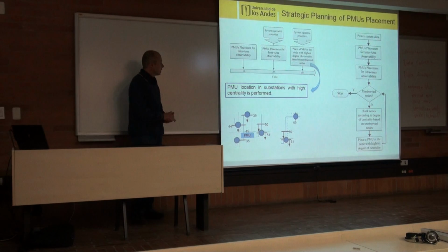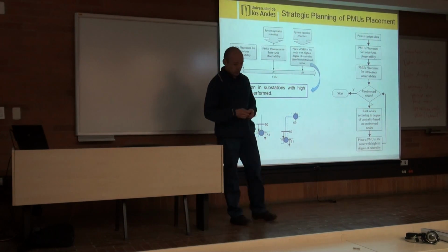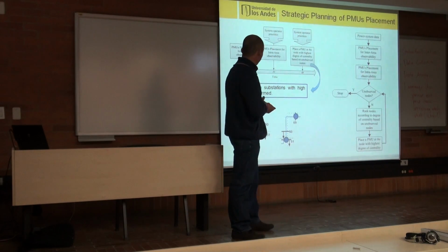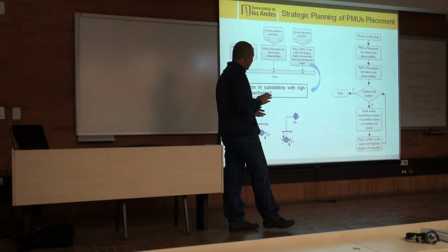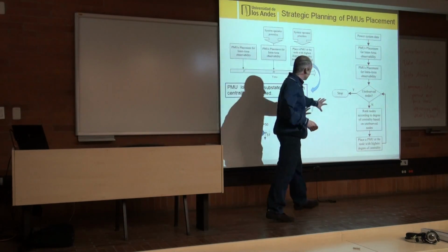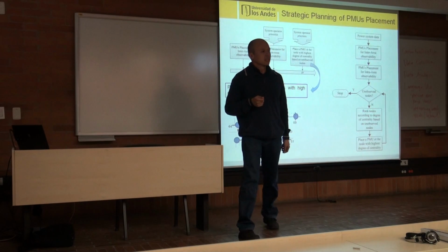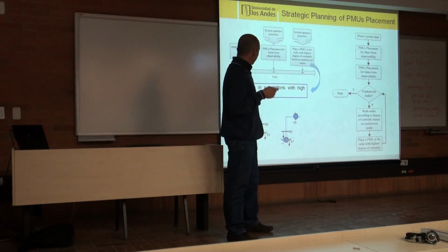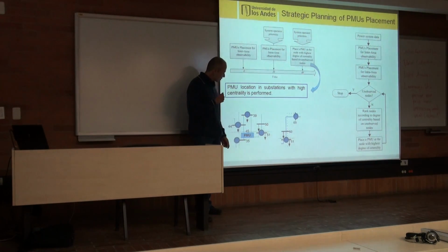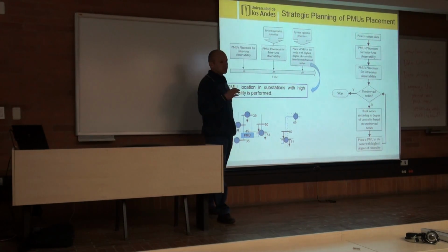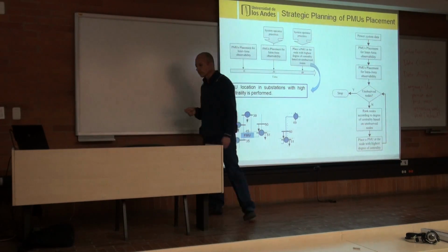And the third part is to find the PMU location for the rest of the system that is concerned at this moment. Here you can see that it is an iterative process that will be done in the system to identify buses that have high centrality in the system. Those buses will be the place to put the PMU.